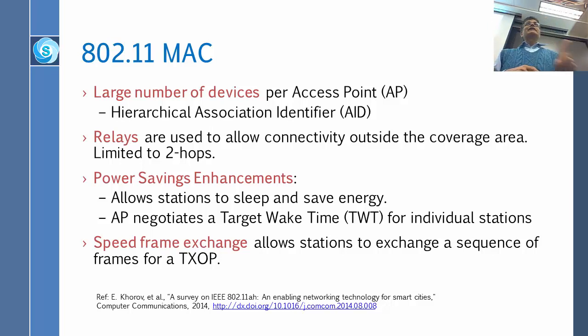That is another trend I talked about in the last class, that people are not going for mesh. Mesh is an interesting topic for academics. All the academics are publishing a lot of papers on how to do mesh networking because it's a good mathematical problem. But in the real world, it's a very messy problem. Nobody wants to send other people's packets using their battery, right? So it doesn't succeed. Here it is a relay, and the relay is not battery operated. The relay could be mains operated, and could be connected to whatever. Its job is just to transfer packets.